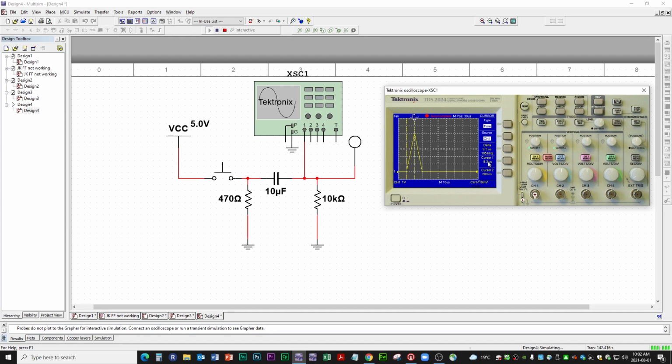You see cursor 1 is at a negative value. That's okay. Cursor 2 is going to be at some value, and what we're interested in is how much time it takes to move from cursor 1 to cursor 2, and that's a very convenient way of showing us. So it's 9.5 microseconds from here to here.